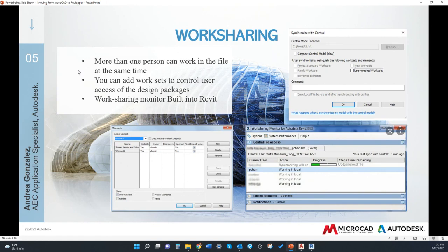Once the worksets and ownerships have been defined, Revit will not allow anyone to delete or alter anything under your ownership without notifying you. So you can be asked for permission and you can allow or deny. This prevents anyone from doubling up on work or trying to delete something that has already been deleted, or just any overlapping of work.